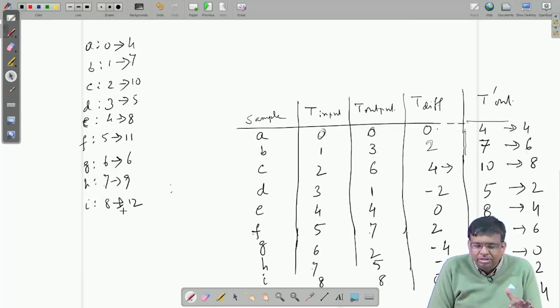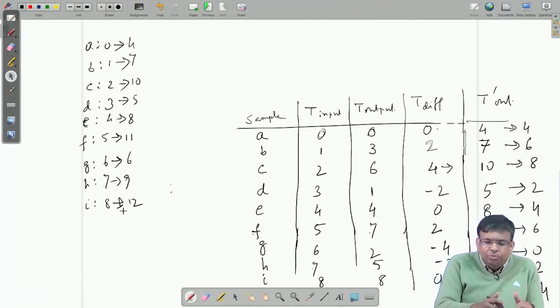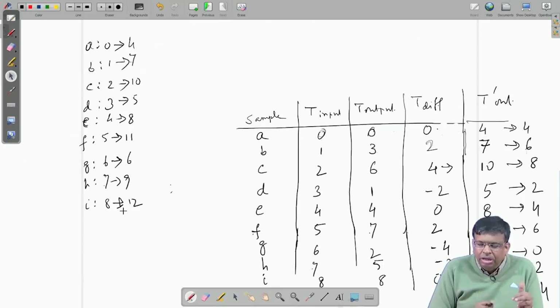All right, but this is only one period. In the Lth input cycle, we read certain elements A, B, C, D up to I of the incoming matrix and had to store them by delay registers in the system over these cycles. But in the very next input cycle, that is L plus 1th, I will have another matrix. Maybe it will have elements A prime, B prime, C prime up to I prime. So, I have to store them also using the same delay register.